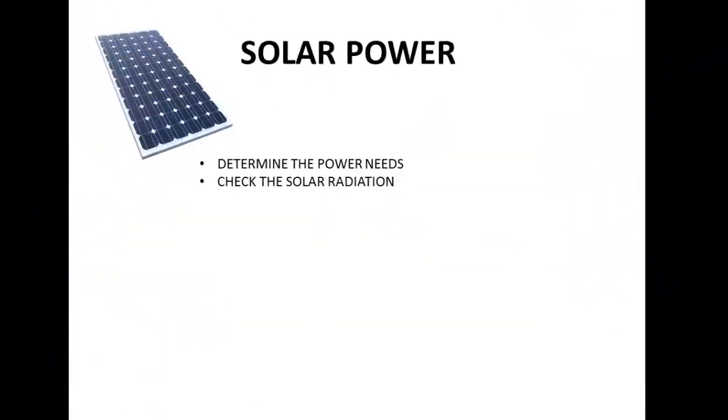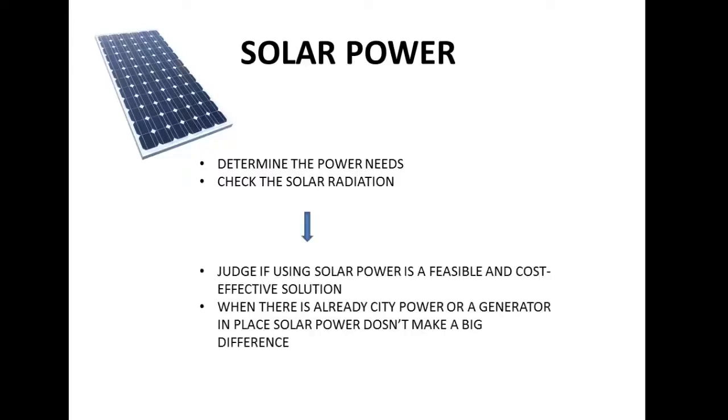Solar power can be considered as an effective and reliable energy source in certain contexts for specific applications. Before considering using photovoltaic panels, you should always check which are your power needs you want to fulfill with solar panels. How many watts for how many hours? Solar irradiation per square meter and number of sun hours in your area. Answering these questions will help you consider if solar panels are really a cost-effective and functional option. Always take into consideration that if you already have city power or generators, solar panels won't make a big difference.